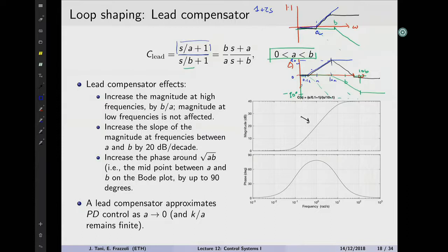That is the amount of things that can happen, in some measure, before your system goes unstable. For example, what uncertainty can you have on the model of your plant before your controller designed for a nominal plant still works? So if you remember, the margin of phase was defined as the difference between minus 180 degrees and the actual phase of the system.